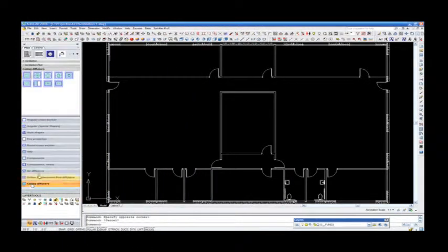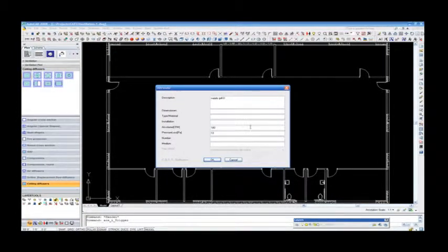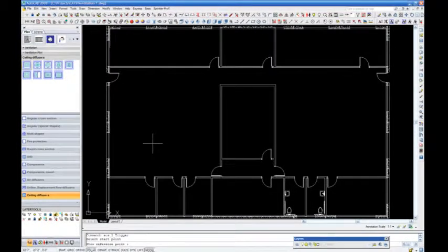We are now going to design the duct system. In the CATS Commander, under Ventilation, click on the drop-down menu for Ventilation Pilot, pulling up the bottom menu. All the components to design your ventilation project may be selected here. We select Ceiling Diffusers and select the first diffuser in our database. In Attributes, we can change our CFM values, pressure loss and dimension, type, material, etc.